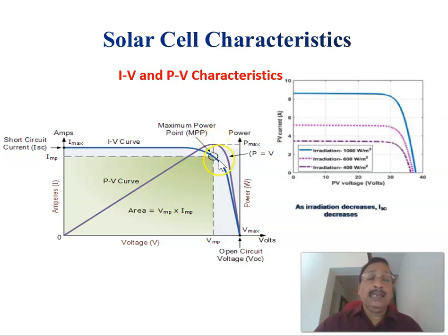And then, as you know, this IV characteristic is dropping here. Therefore, the product begins dropping, and the PV curve drops down and reaches this point. Therefore, this is the PV characteristics corresponding to this IV characteristics. This is the maximum power point, or the maximum power.